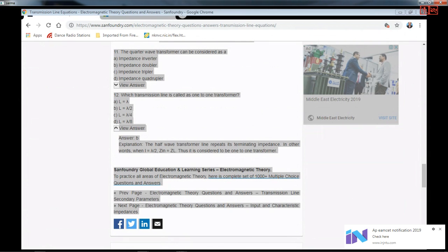Okay, so the voltage minimum. Why do we choose it? We could get the same things from the voltage maximum. Corresponding equations can be developed for the voltage maximum also, right? But we try to choose only the voltage minimum because it is sharper. As you move along the transmission line to find where the voltage minimum is, the slope of the characteristic across it is very, very high. If you see the variation in the electric field or the voltage wave across this location for various distances, the voltage changes are quite small. So the slope is very high, and you can precisely find out where the voltage minimum is.